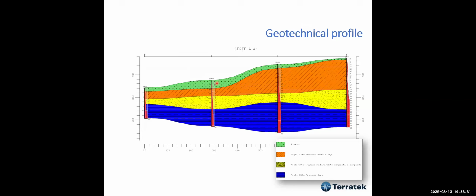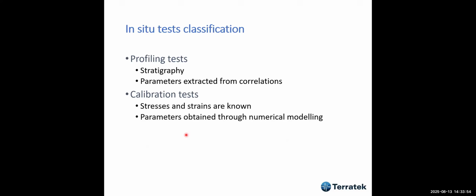An example, and here the SPT values, as you see, in the field they are very low. They are mediums from 7 to 10 here in this clay. In the sand, it varies from 15 to 30, nearly 30. So this is what, as a geotechnical engineer, you want.